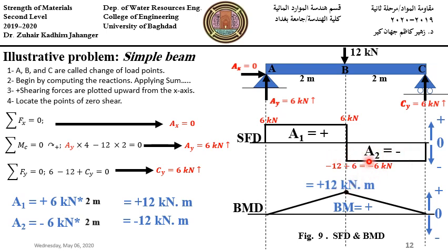We have a uniform shear intensity. We draw a straight inclined line between B to C, because we have uniform shear intensity. So the final bending moment for this beam is positive, so we will get a sagging deformation.